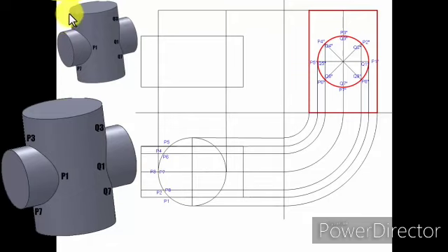When you try to look at this from the top, you're going to see point P3. Just below P3, you're going to have point P7. That's why I've written P7 also over here. Similarly, you're going to write P2 over here, and just below P2, you have point P8. So hence P2 with P8. Similarly, all the points over to this side also can be worked out in this way. That's it. It's pretty easy. And now the only thing left is to have the curve of penetration in the front view.